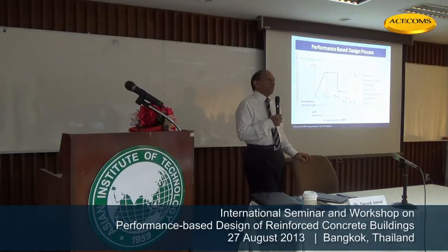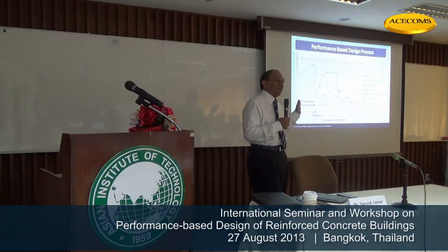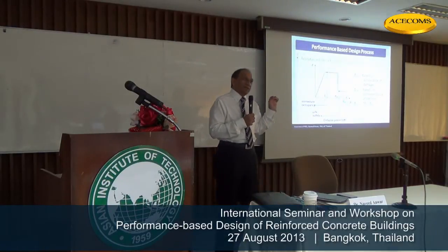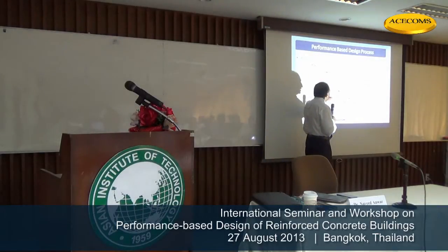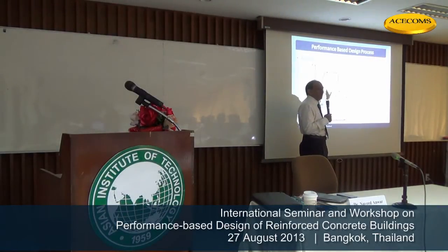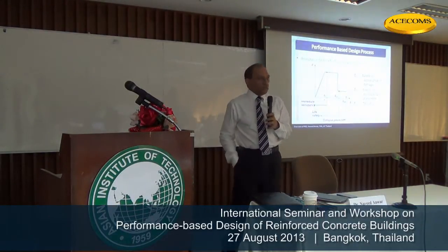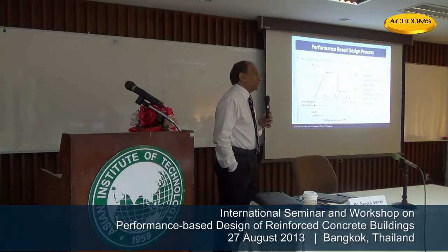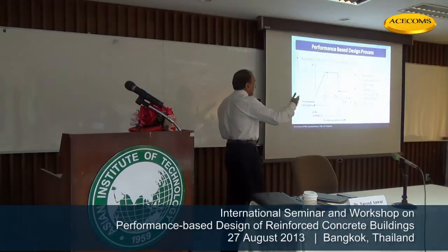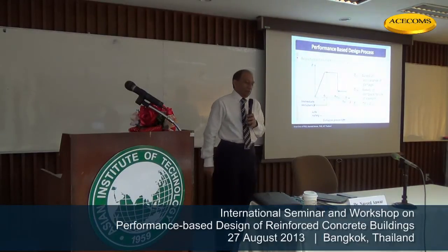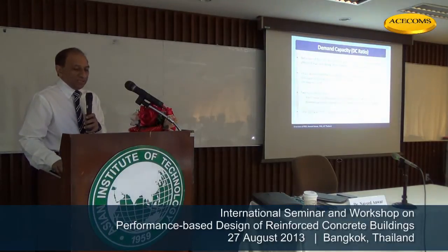So some owners can say that, okay, I will accept this cost, and you can bring back my criteria. So that is the fun part in performance-based design, that these limits can be moved back to this side, depending upon the client's interest, importance of the structure, or the money that they have. So performance criteria can be adjusted based on what is expected of that structure and what kind of money or resources can be spent.